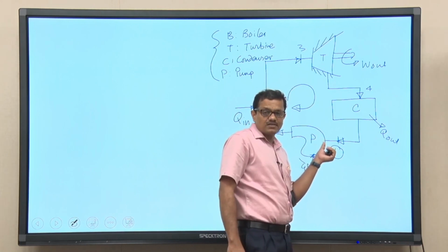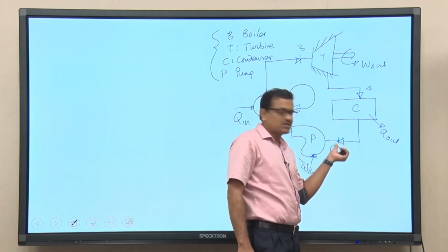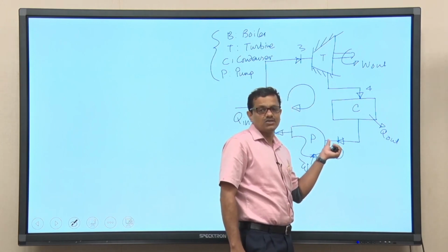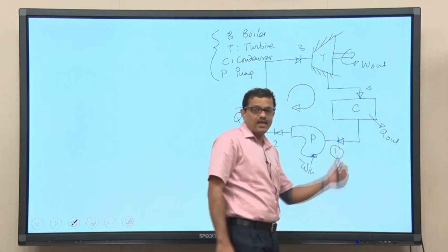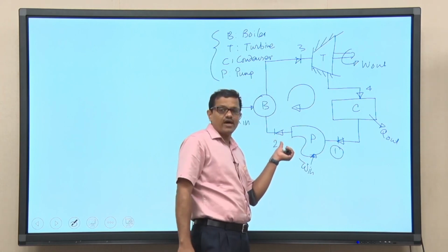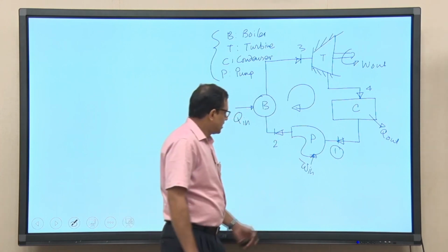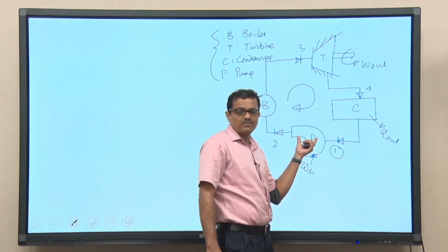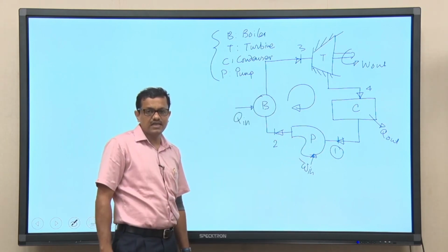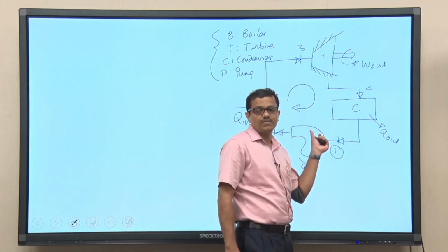Can we represent the process by a reversible isothermal process? Because you know that the thermodynamic state of the working substance at point 1 is saturated liquid. So, while pumping, the state is getting changed and it is coming to state 2 where pressure is definitely higher, and that is what our objective is. But since it is an incompressible fluid, there is no change in specific volume. But can we really represent the process by a reversible isothermal process?